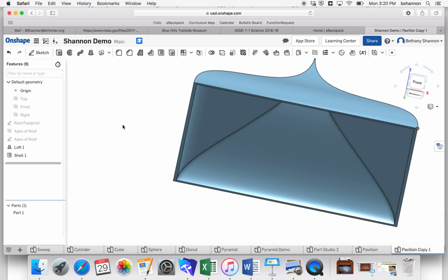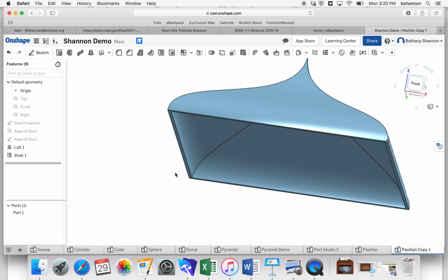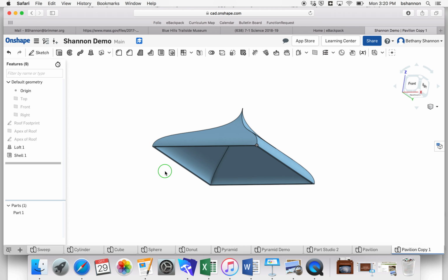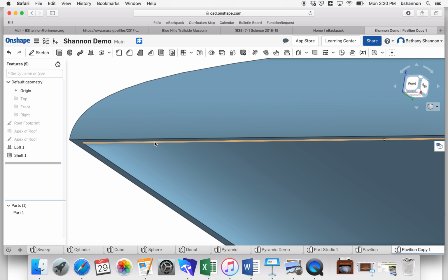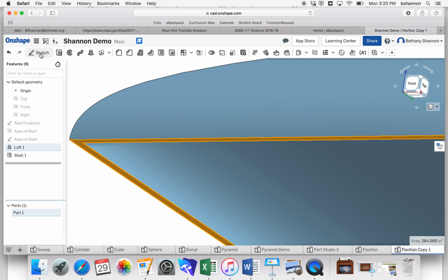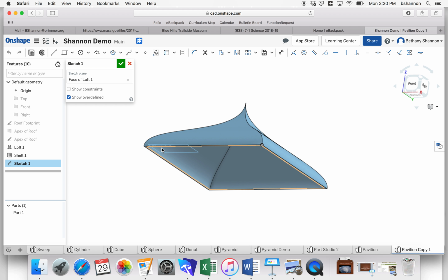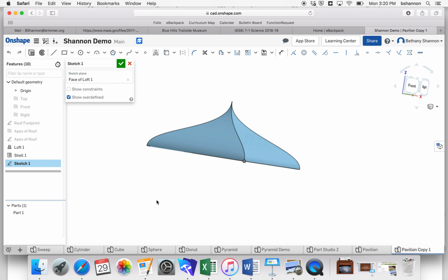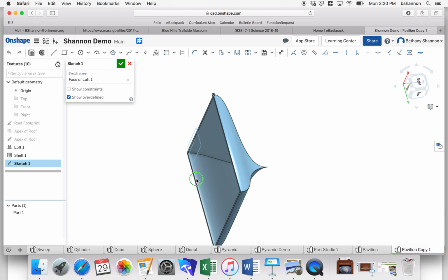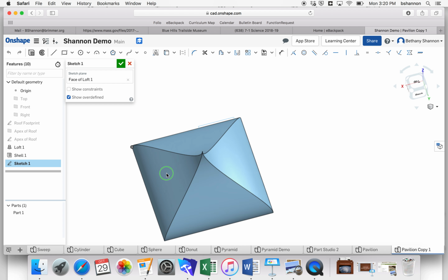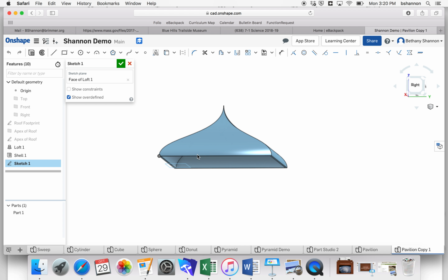The next piece is you are going to take and build some pillars to support this roof structure. So I could build the pillars right off of this surface using a sketch plane from this surface. So I click that, open up that sketch plane, and then I could build the pillars downward. The problem with this, however, is that there's going to be this gap where the pillar never really reaches the roof. Not realistic and not good design. I do recognize that there's construction issues with the way I'm doing this. However, I think the better choice is to have that pillar continue all the way up into this roof structure.